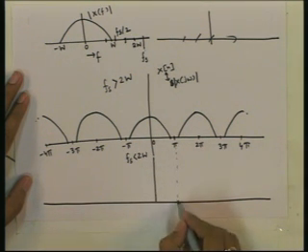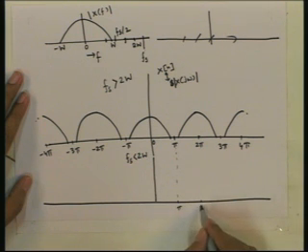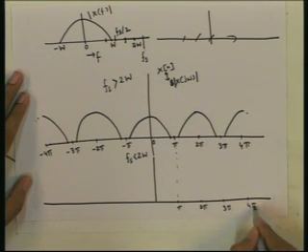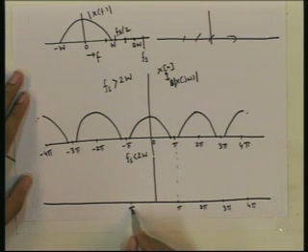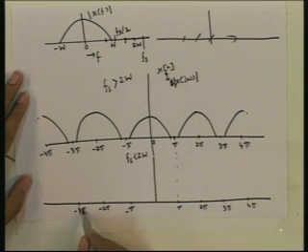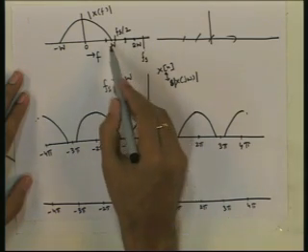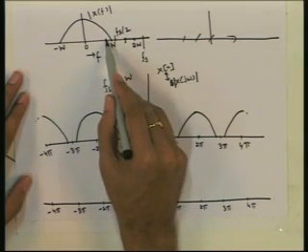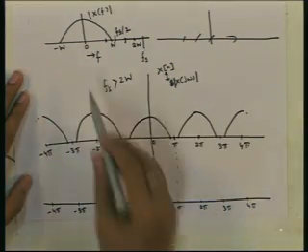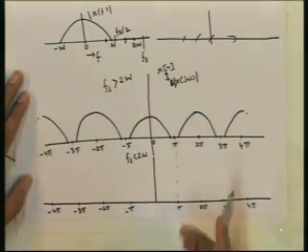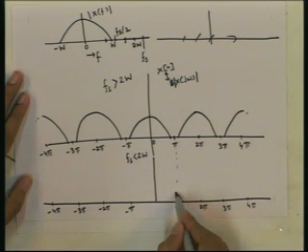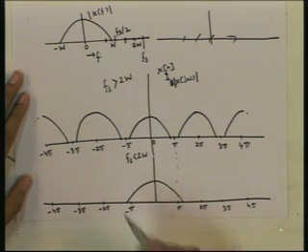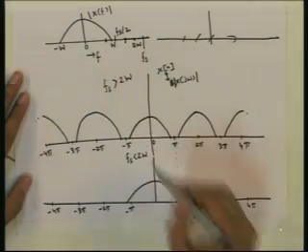In the same frequency scale, pi, 2 pi, 3 pi, 4 pi, minus pi. So this Fs by 2, which is less than W, will be mapped to pi. So the copy of this here will look like this, because this Fs by 2 is mapped to pi.